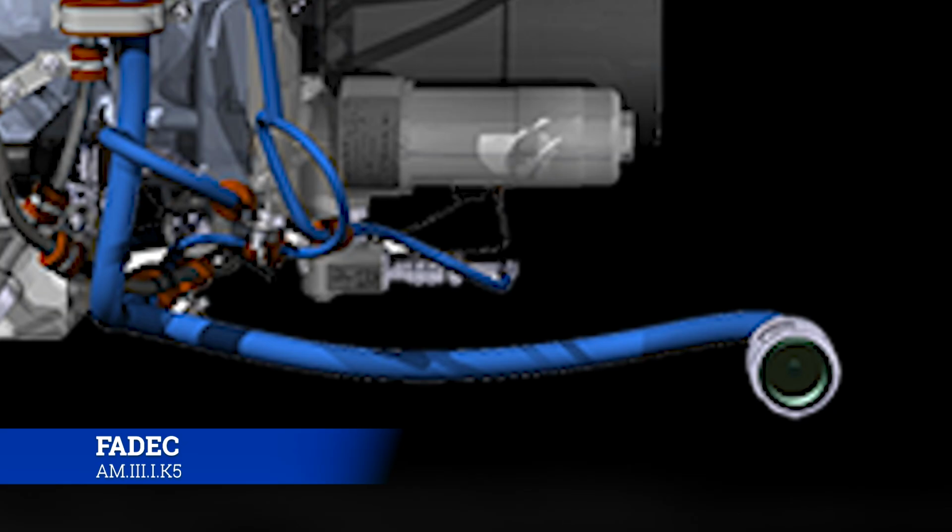You simply just pull the collective up. Whenever you run it, you start the engine up. Once it gets above 90% NG, the PMA kicks on, and then from then on, it's going to keep on doing its thing no matter what you do to it until you go to shut it down, and there's a shutdown sequence to turn it all off. That means that you can pull the collective up, you can drop the collective down, you can yank and bank, you can put all the load you want on the rotor, and that FADEC system is going to say, I need to be generating so many RPMs no matter what.